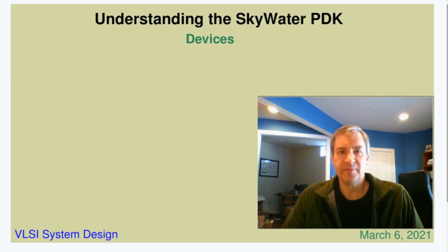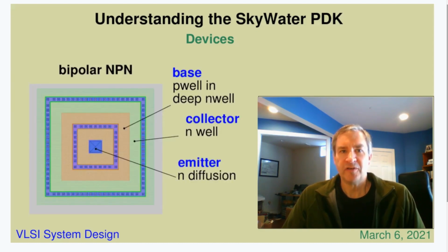Understanding the devices is important for physical verification, since much of the physical verification is concerned with correctly identifying and extracting all devices on a chip. I already discussed some devices available in the SkyWater process, namely thin oxide and thick oxide MOSFETs and MIM caps. Like most larger feature-sized processes that are good for analog and mixed signal design, the SkyWater process has numerous device offerings for resistors, bipolar devices, capacitors, and so forth.